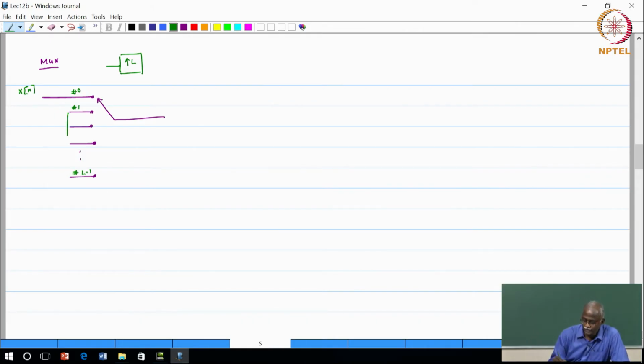So, what I say is connect all of these to, just like circuit notation, ground. So, basically that has a value 0. This one can rotate counterclockwise. You take the input sample from the input stream, and then you insert L minus 1 zeros, and then pick up the next sample, again L minus 1 zeros, a systematic way of operation.